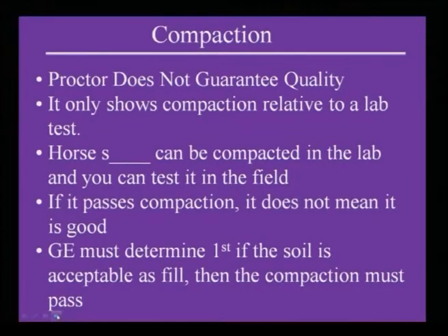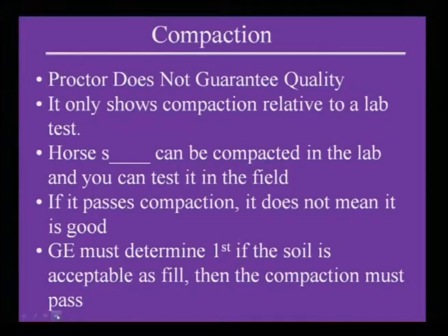The Proctor test, whatever you are doing in the laboratory, is a very small test. It does not give you any guarantee of the quality to be maintained in the field. It only gives relative compaction. A geotechnical engineer must determine first if the soil is acceptable as fill, then compaction must pass. If it passes compaction, it does not mean it is good.